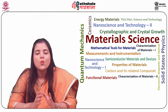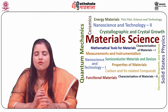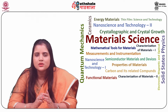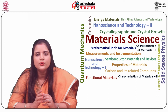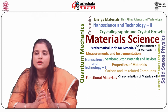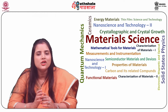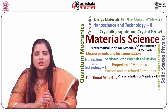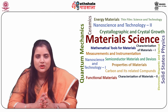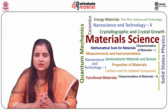For instance, when a crystal associates with an electron to supply a flow of electrons or holes, that is electron extraction, a voltage is applied to a p-n junction, producing a flow of current. That means electrons are flowing from the n-type material into the p-type material. Electrons lose energy when they recombine with centers or positive holes, thereby emitting light.